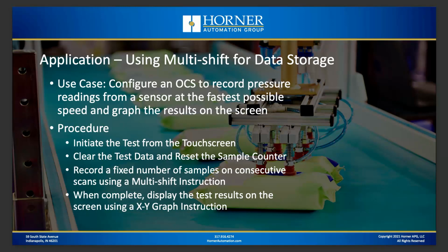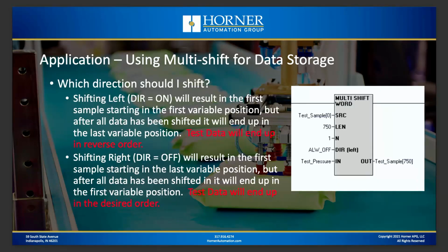And then we're going to want to take that data and put it in an XY graph instruction so we can view it on the screen. So that's our process. Now, one of the things that's often difficult to deal with, or at least to get your head wrapped around, is what direction do I want to shift when I am storing away my data? So let's think through that for a minute before we actually go in and start setting up our ladder logic.